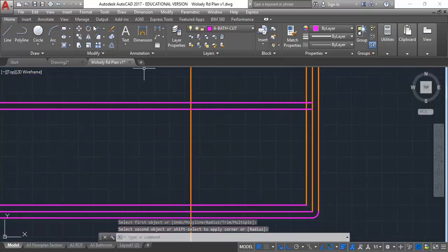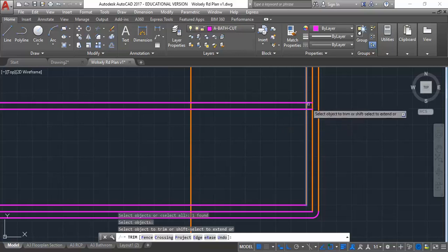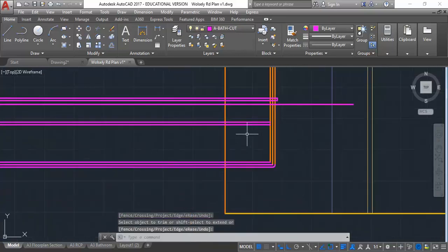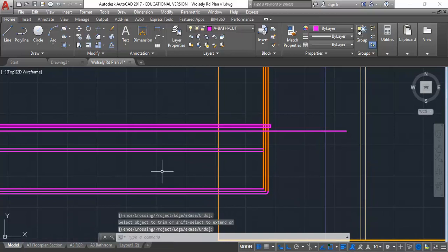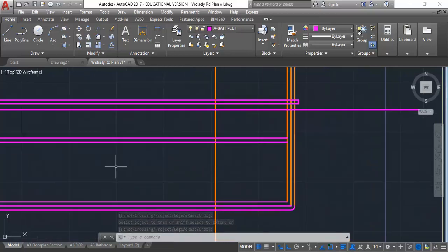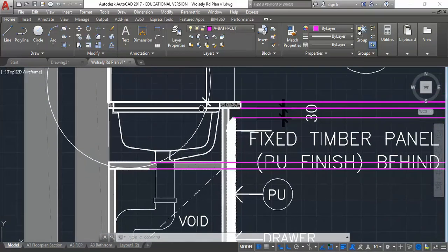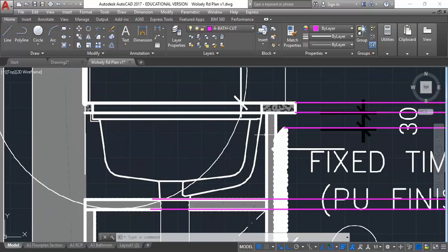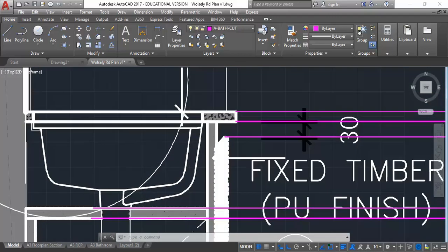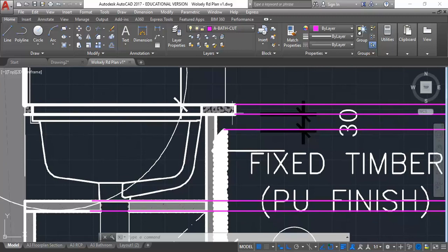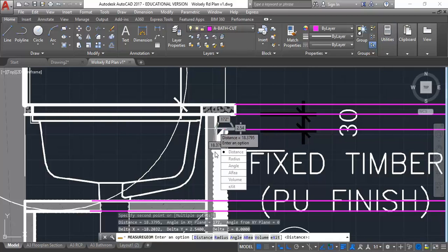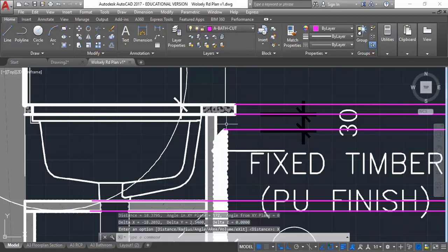It's difficult explaining these things, but when you are drawing them, it should become fairly clear because you're essentially just projecting either from the plan or from the section. You can see that I've got most of the lines of that vanity unit, so there's a few more I could project off here. Also I've got the front there, so I've just assumed that's 20 mil. It could actually be more, but I'll keep it 20. Oh, it's actually okay, so yeah, we'll keep that 20.